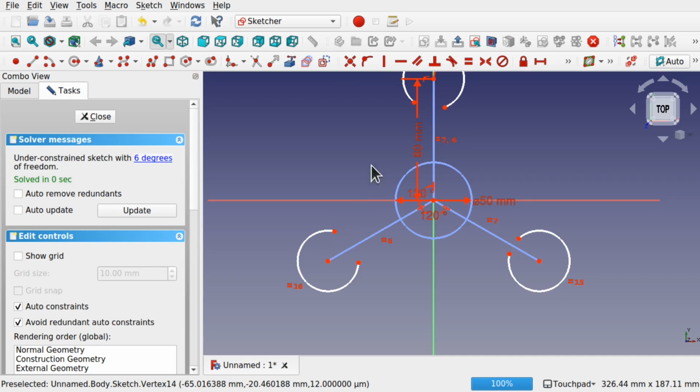So we're going to connect these up with an arc and then touch this circle in here, so they're tangent to here. Let me show you. We're going to use this time an endpoint and rim point. Make it coincident, so that point coincident to that point, and we're going to come down with the arc and then touch the inner circle. That makes that tangent to that inner circle. Tangent means touching, it's touching that inner circle.